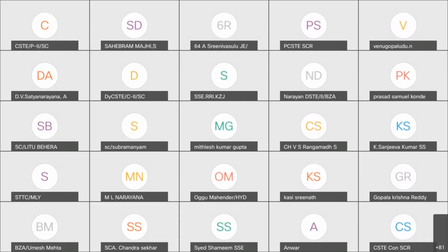Sir, actually in TWS point machine installation, we are going to install with the existing supplied MS plate and gauge plate, but if we install as per the dimensions of the RDSO drawing, the rods and throw bar cannot be fixed square and perpendicular to the tracks, exactly. So for this we are making another 4 holes for MS plate fixing on the fourth sleeper, and according to that we are installing for this square purpose, sir. To overcome this, the widening is needed: the supplied MS plate is 220 mm wide, but we require a 250 mm MS plate, sir.